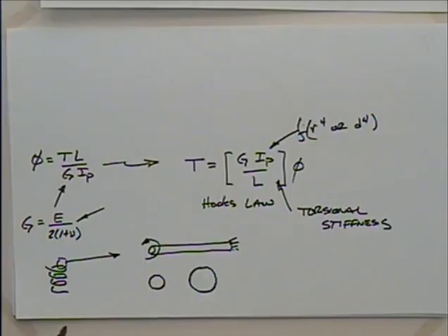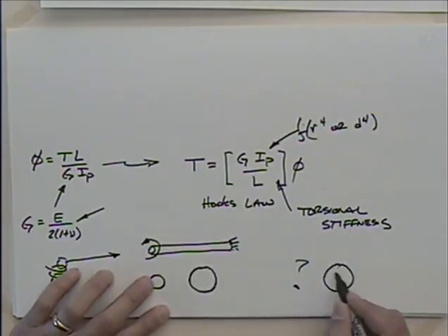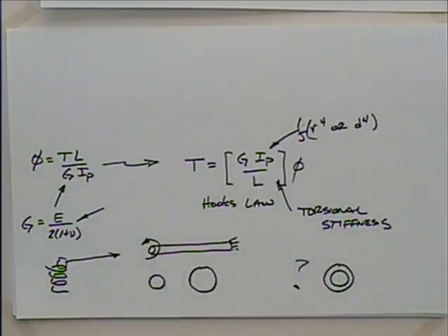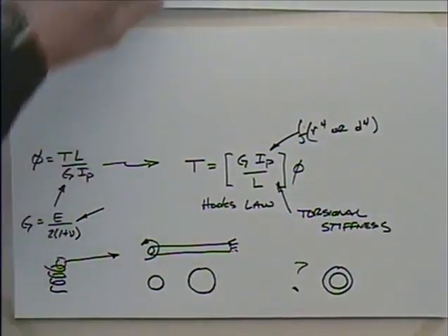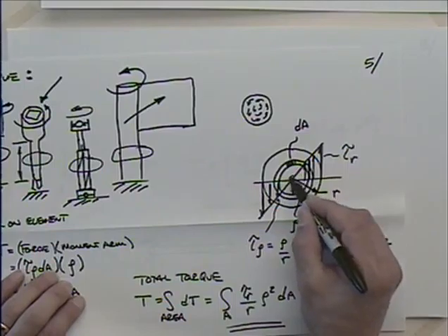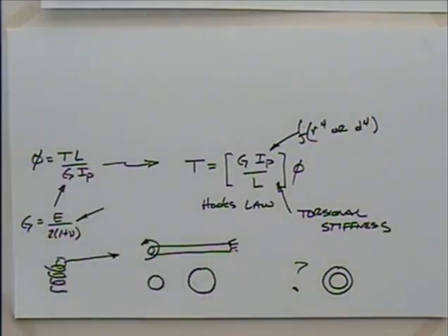What we will do when we get together next time is look at what happens with hollow shafts. A lot of you might say, I've got a drive shaft and it's hollow. What's going to happen there? There's a lot of lore about this, that it's more efficient because you have 2 surfaces to bend on. It's technically not more efficient, but it is way more weight efficient, because if we go back and look at our original picture, the center here does not do a lot, so we actually get rid of that. We'll look at some examples of hollow shafts and see how they can be quite a bit more efficient from a weight standpoint. So that's where we will go next time.